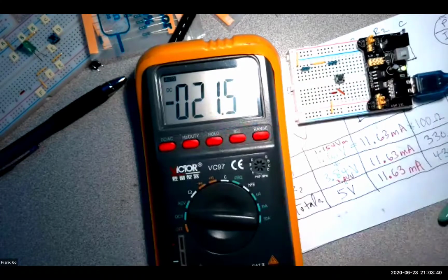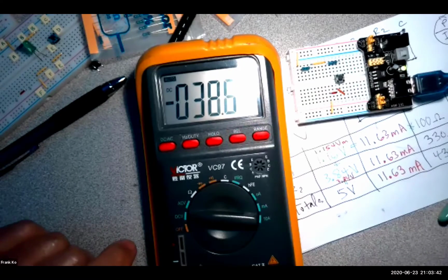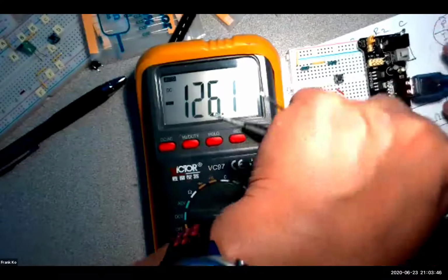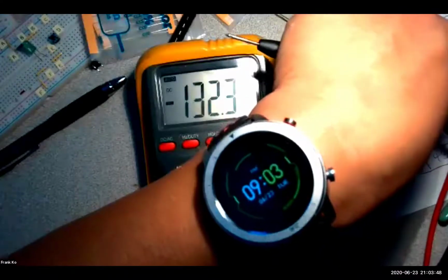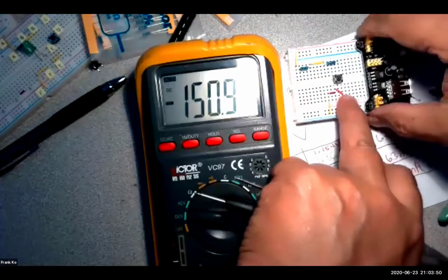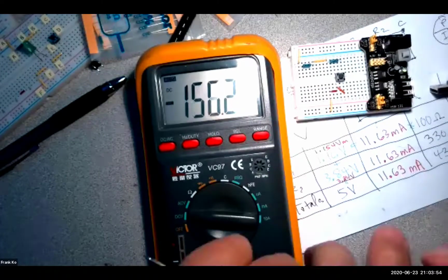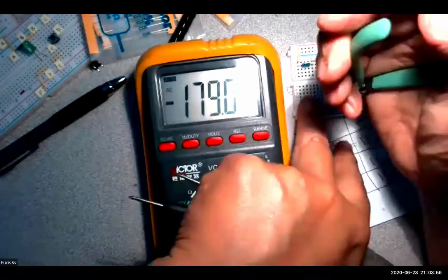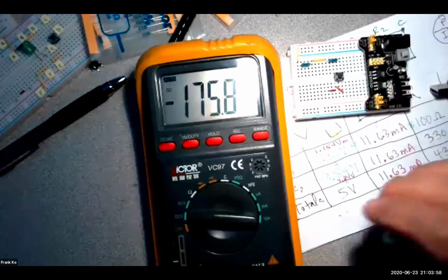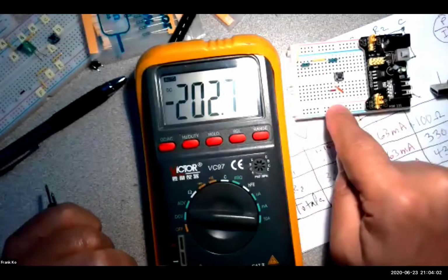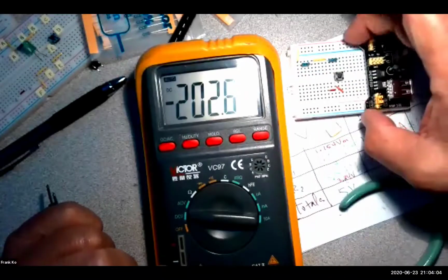All right. Now, to measure your resistors, to make sure your resistors are correct, turn off the power supply and disconnect the USB. Actually, you can either remove the power supply, or what you ought to do is move the connection. I remove the jumper wire at the bottom of the circuit. Now there's no physical connection of this circuit to the power supply.